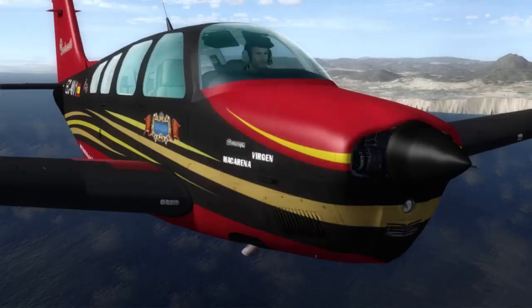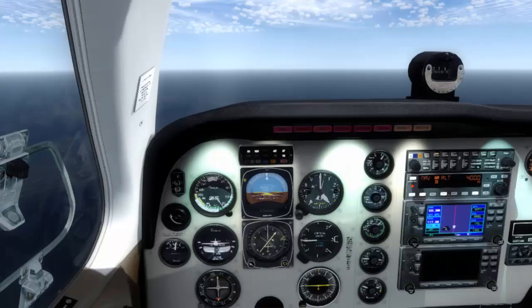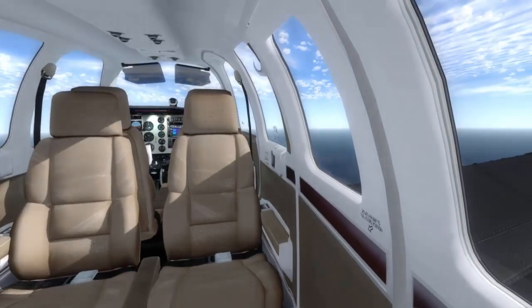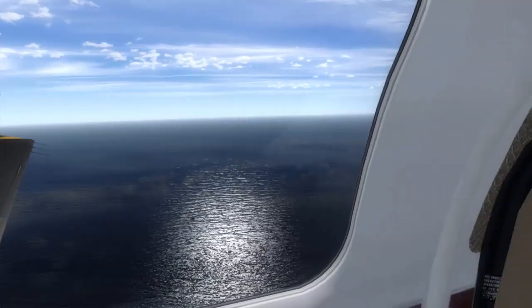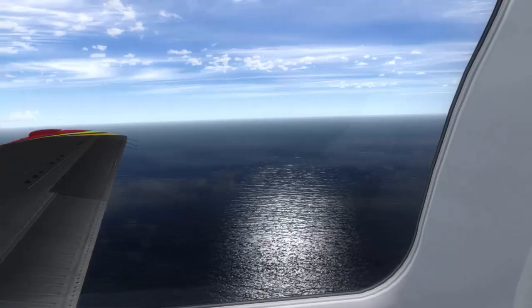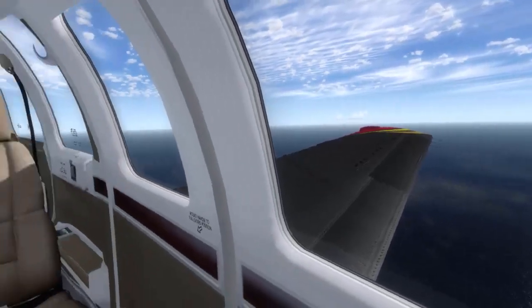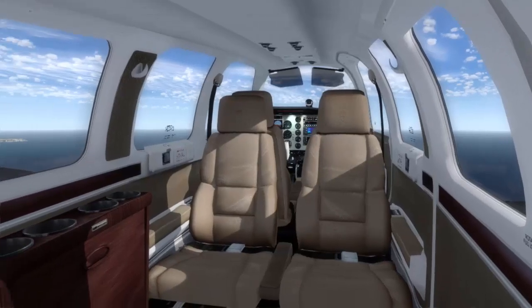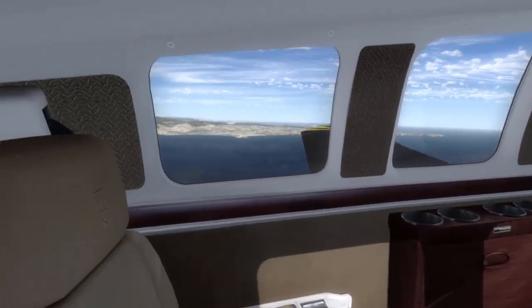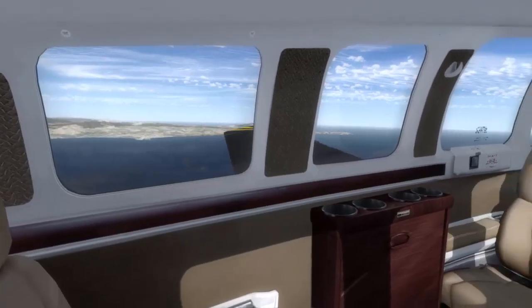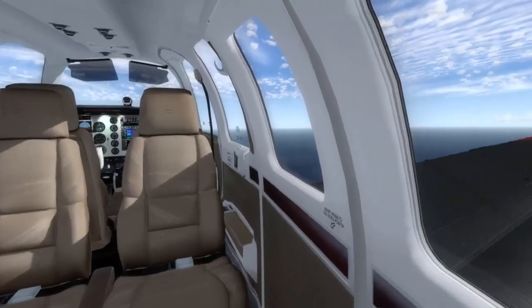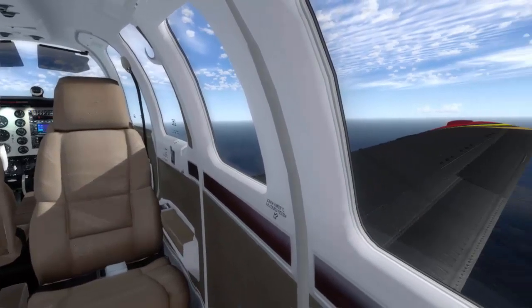What I was telling you, and I prefer to talk about this because this is what really matters here, is that many airports have a VOR close to the runway, and to align with the runway through a VOR DME approach, you need to follow a certain radial that is crossing in front of the runway. So when you follow that radial, you get aligned with the runway.